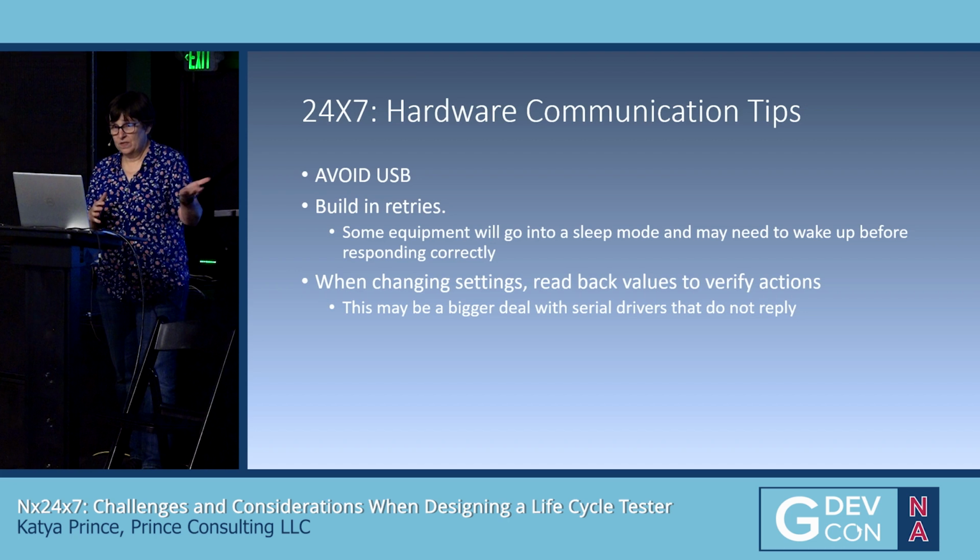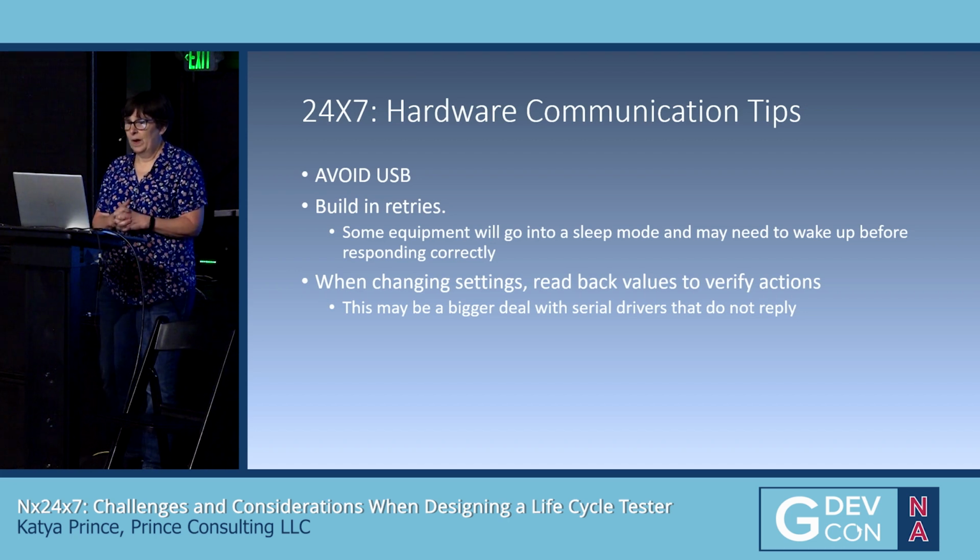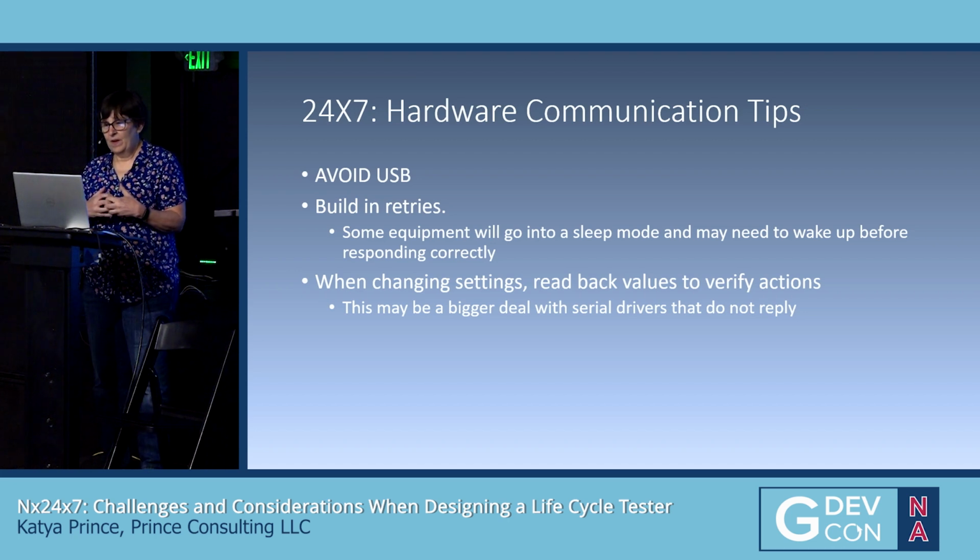If you are going to be changing settings, like on a power supply, you should read back the values to verify. This really depends on your driver, and it's a bigger deal with some of the older serial drivers because they didn't necessarily respond. So you could send out a write, and the serial port's there, the write's all good, but if there's nothing on the other end, it's possible that you aren't doing what you think you're doing.